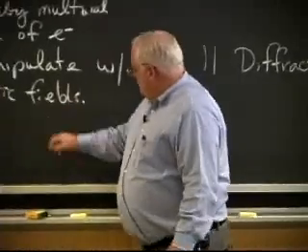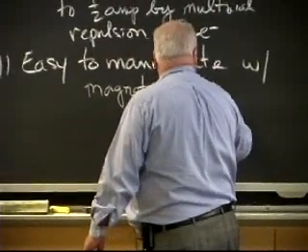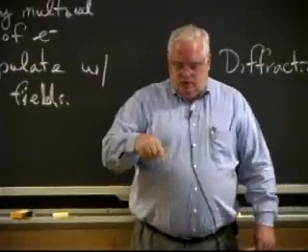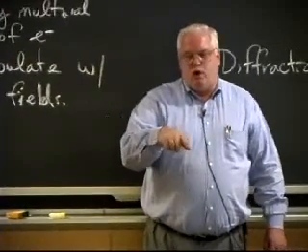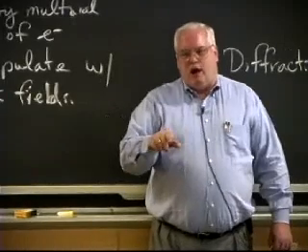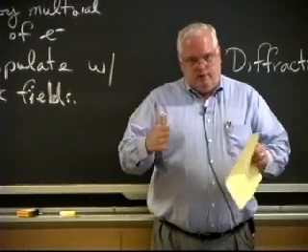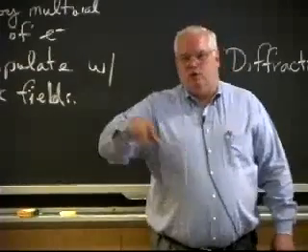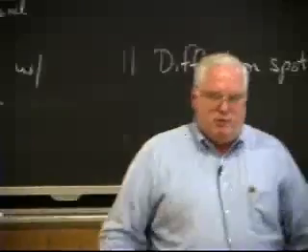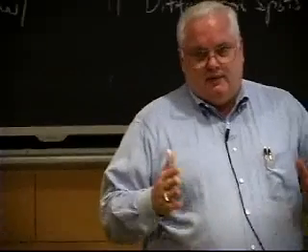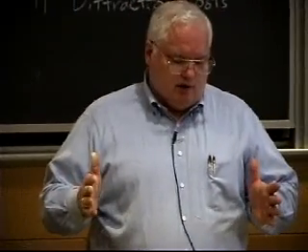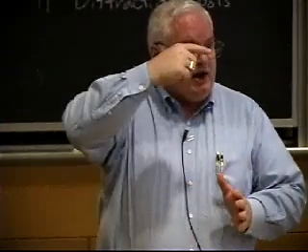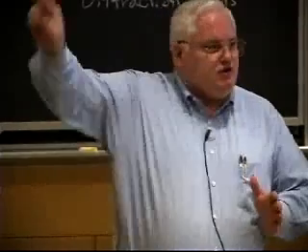So far as manipulating this with the magnetic fields, typically on a laser beam welder or a laser surface hardening apparatus, you can just apply an XY field and you can scan the thing wherever you want. In fact, I had a student once studying electron beam welding of stainless steels, and the laser they had out at Lawrence Livermore, where he's working, basically could sweep at 1,000 inches a minute. They just had a magnetic field. I mean, the beam came straight down, but the magnetic field just deflected it.